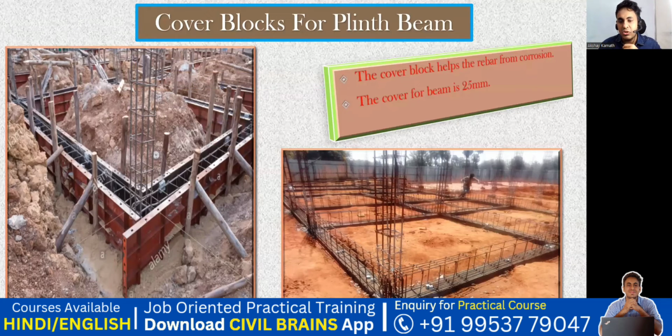So this is your 12 diameter 1 bar, which will go completely. And this is another 12 diameter 1 bar, which will go completely. Another 12 diameter 1 bar I'm supposed to put, but not completely. It will go up to 3 feet 4 inch. Can you see one more bar at the center, which has been stopped here? So this is your 12 diameter 1 more bar, but it is stopped at the 3 feet 4 inch distance. Very simple.